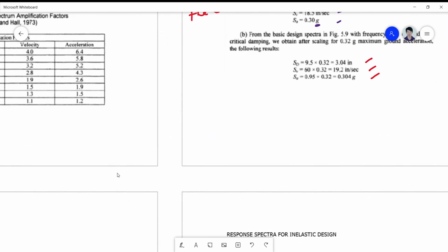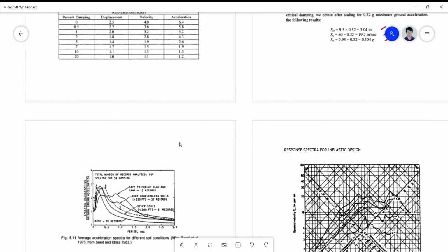So in Baguio, I noticed that their acceleration is very close to scaling. The scaled acceleration, the peak ground acceleration, is actually 0.30 to 0.35 g. In Tarlac, I'm using 0.20, but somebody told me that it's safe to use 0.30 as your peak ground acceleration, even if you're not in a place like Baguio, because it's amplified by the height of their terrain. The acceleration is higher because they are up high, supposedly. I really don't know the basis for it.